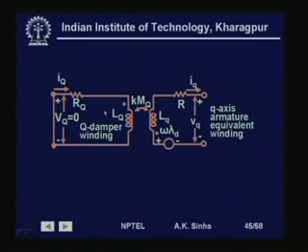When the damper current dies out, we have only the Q axis current flowing. So, we have a subtransient and a steady state or quadrature axis reactance, the synchronous reactance of the machine. So, we have XQ and XQ double dash, which we use for the subtransient part. XQ dash is generally not there.